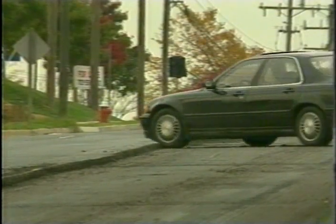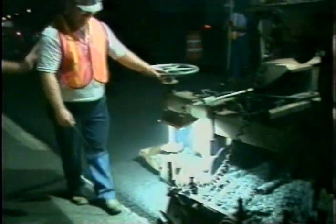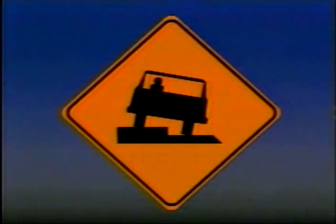This situation requires some special attention. There are several precautions to take. Avoid drop-offs greater than 5 centimeters left overnight and immediately adjacent to traffic. They have a high accident potential. Specify that the contractor schedule resurfacing or construction operations so that no drop-off is unprotected overnight. Place a wedge of material along the face of the drop-off. The wedge should consist of a stable material placed at a slope of 3:1 or flatter. Put drop-off warning signs in advance and throughout the drop-off treatment.